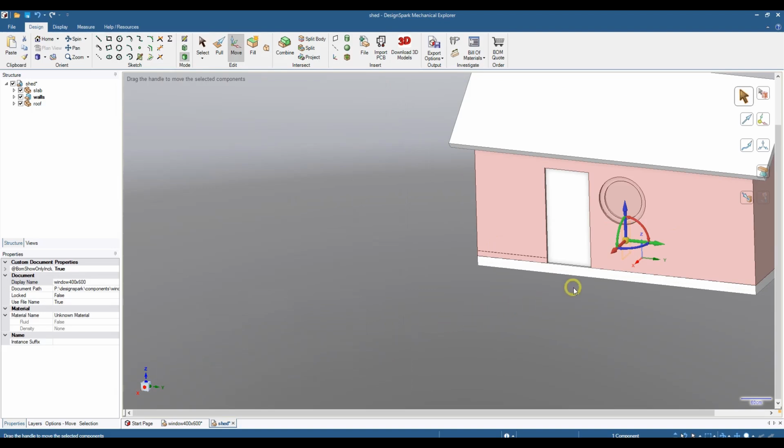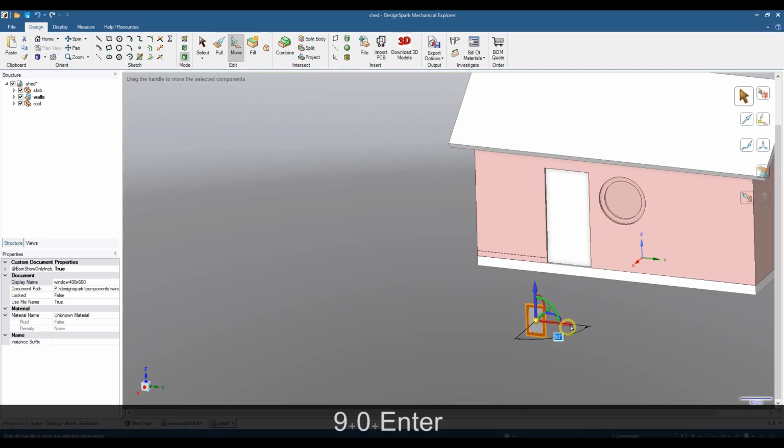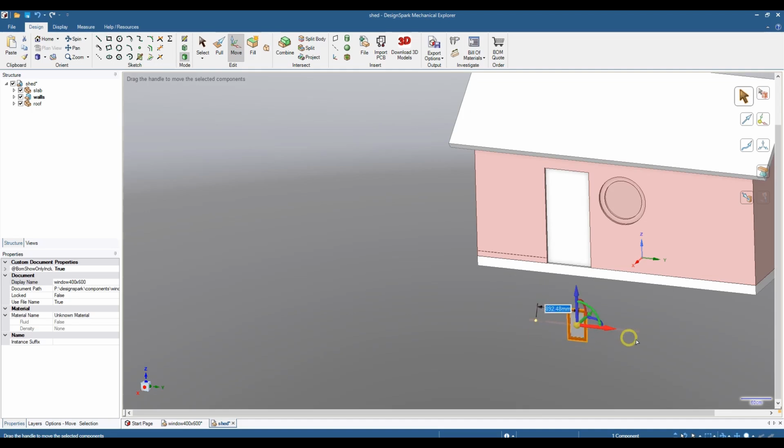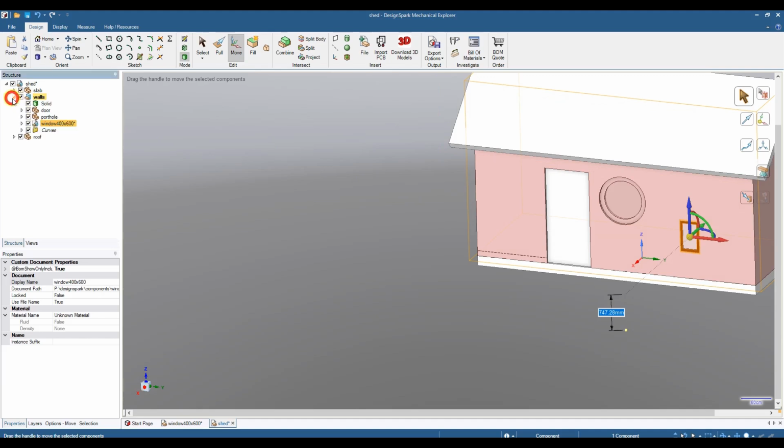It will be imported in the middle of the walls. Also pull on the Move handle to bring it into the open. Notice that the window is imported with its original colors and textures. We can see that it is not oriented correctly, so use the horizontal rotation handle to rotate to the next orthogonal. In this case, rotate the window to 90 degrees. Use the Move to button to place the window on the wall. You can position accurately with construction lines. You will notice that the window is imported as a component in the Windows component.